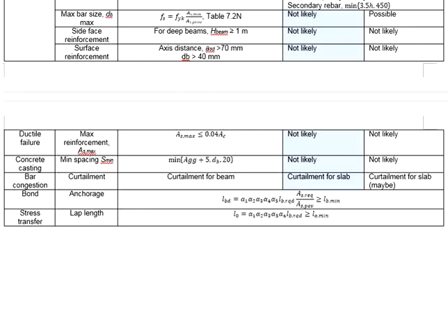regions where the reinforcement bar is not necessary. At the same time, you prevent the congestions of the reinforcement at the joints between the structural elements. You know that the structural elements, beams and slabs, are connected to each other and cast together. At the joints, there will be reinforcement bar from different structural elements meeting each other. Curtailment can reduce the amount of reinforcement bar encountered at the joints.